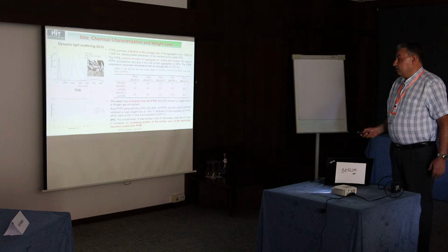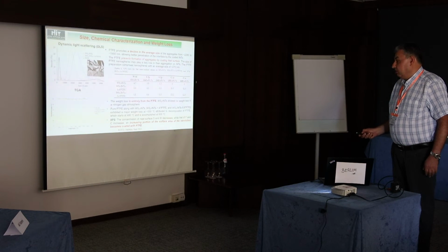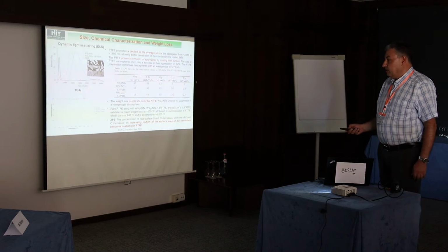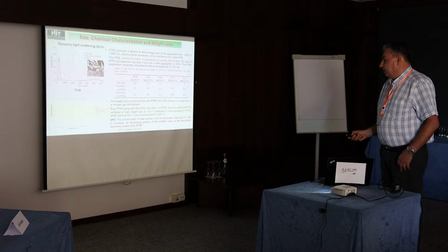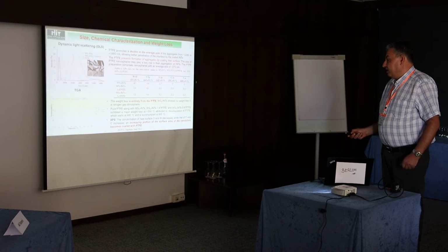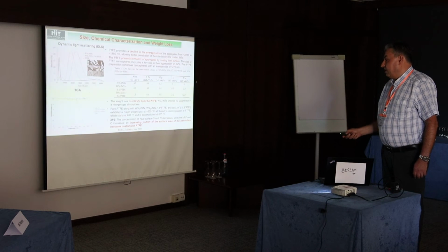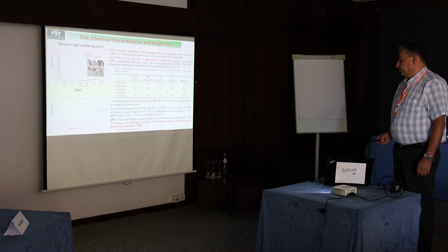And thermal gravimetric analysis also showed that the weight loss is entirely from Teflon and not from nanotubes, because they are very stable up to about 1000 degrees, so even up to 500 degrees there is high thermal stability, and only after this is there a decrease in weight due to Teflon.